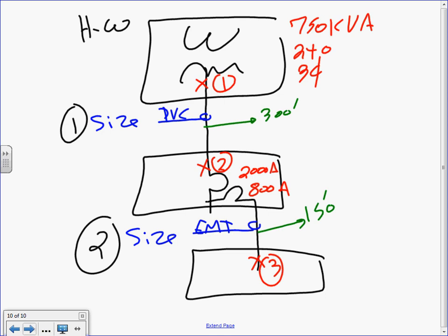So the impedance, let's use 2.5%. We're using a 2.5% impedance. It's an efficient transformer, 2.5% impedance. Am I missing anything? We have the impedance. You guys will size this conductor, use PVC. Which PVC, guys? Always use PVC 80. PVC 80, EMT for the feeder. And size that system. Any comments, any questions? Yes, sir?